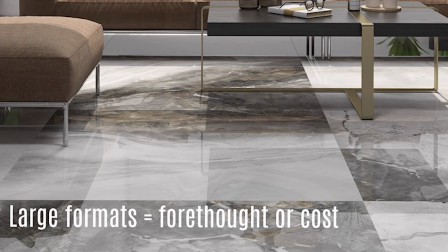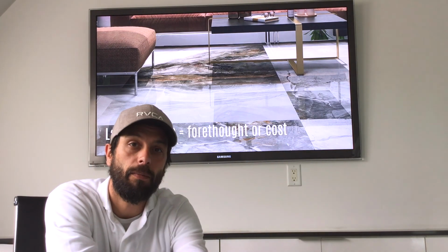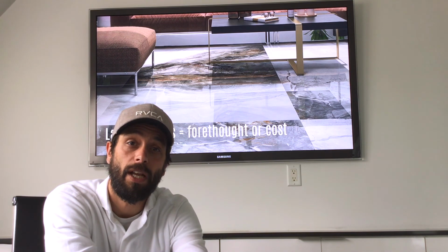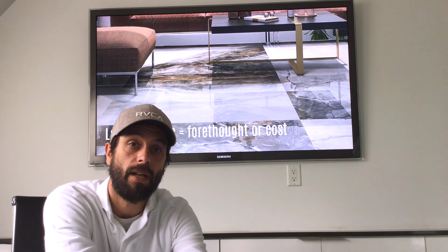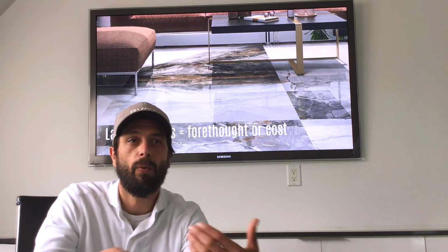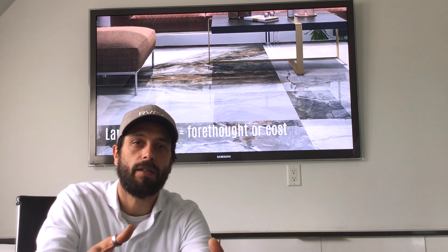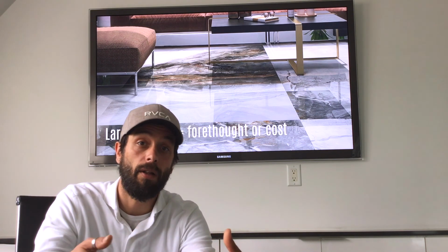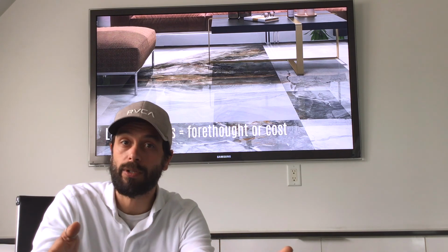And what I mean by that is if you want to utilize a large format, whether it's gauged large porcelain slabs or simply a 1 meter by 1 meter or a 2 foot by 4 foot, those kind of formats, as we get into the larger formats, the earlier we think about them, the earlier we get our trades involved and we set our substrate tolerances, and we screed floors instead of pouring them and then doing self-leveler, the more we can think about optimizing for these large formats earlier, getting our tile installers in earlier on a closed site.